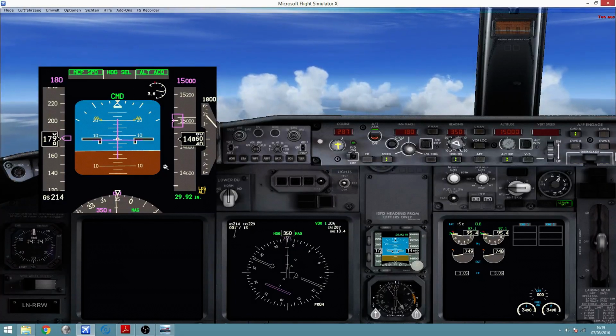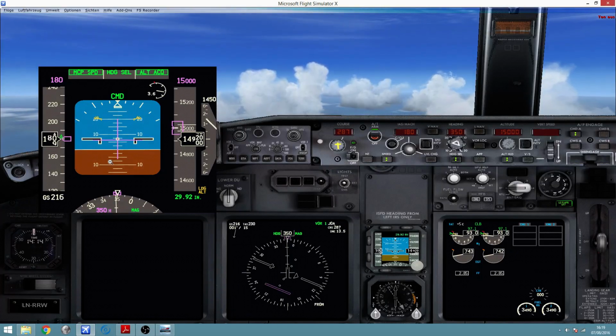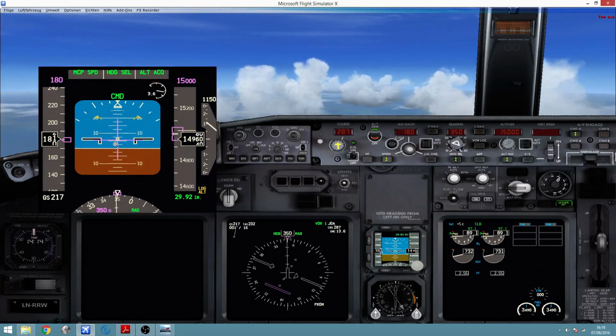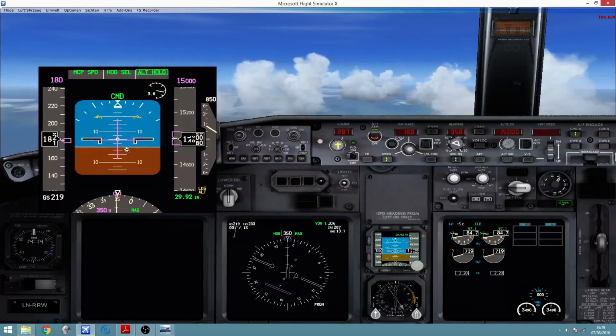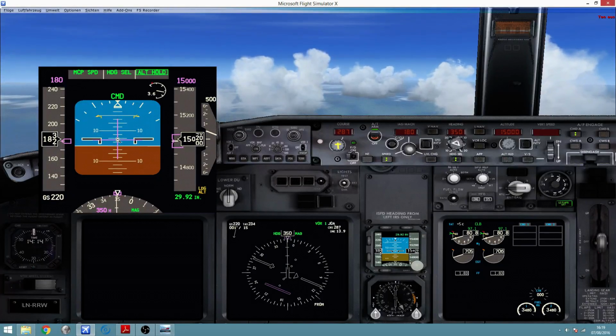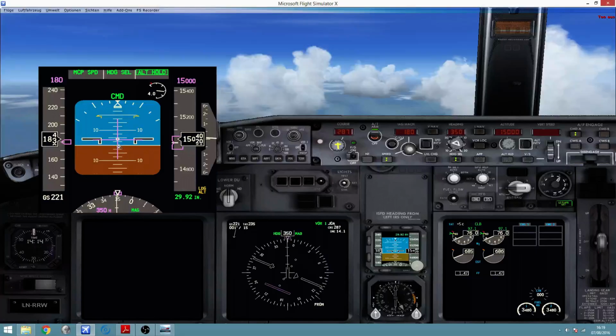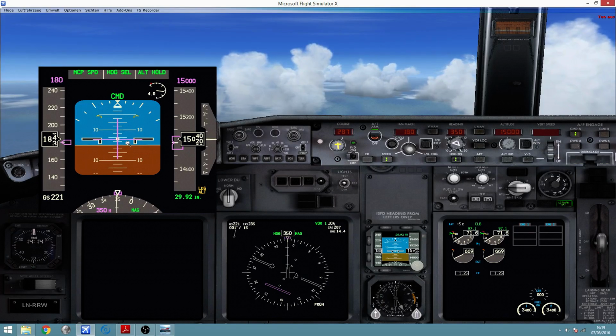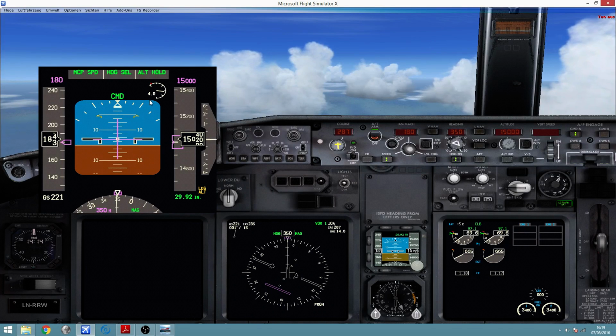We have the artificial horizon that gives us a clear depiction of the attitude of the aircraft with respect to the horizon. This is the current pitch angle of about 4 or 5 degrees now: how the x-axis, the longitudinal axis of the aircraft, is placed with respect to the horizon. This indicates the angle of attack of 4 degrees currently, and this is the barometric altimeter.